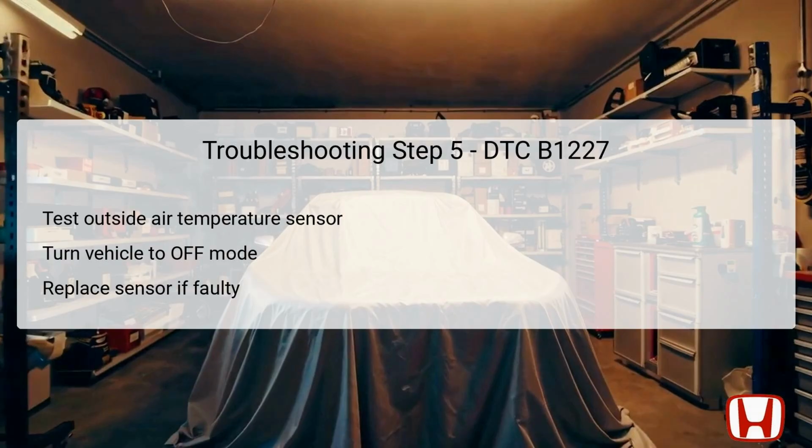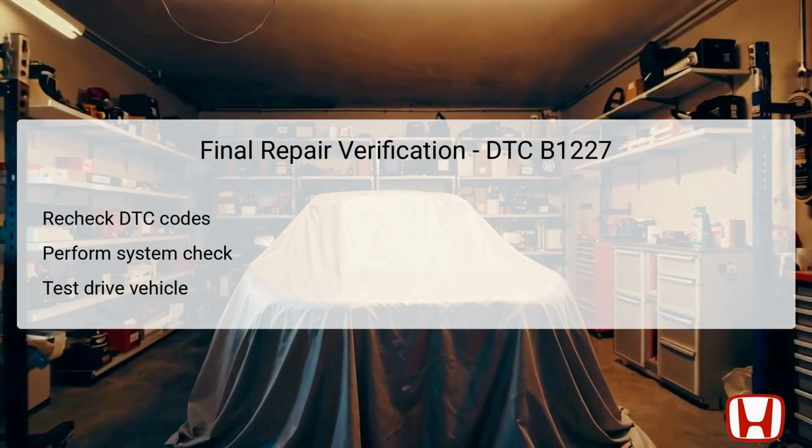After completing all necessary repairs related to DTC B1227, a critical step is performing a final verification to ensure that the issue has been rectified. Start by rechecking the DTC codes using the HDS to confirm that no new or recurring codes appear. This step is vital to ensure that the repairs have indeed resolved the original problem.